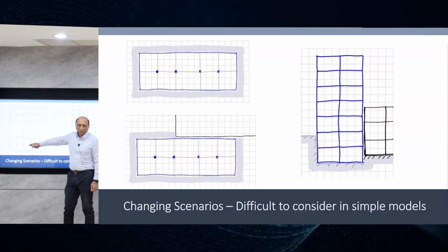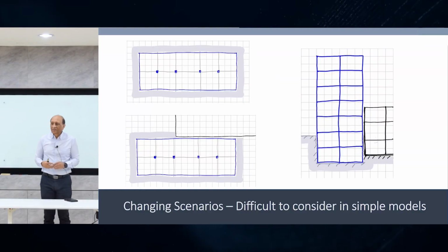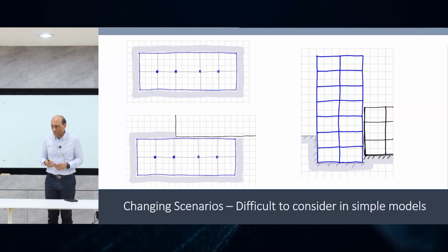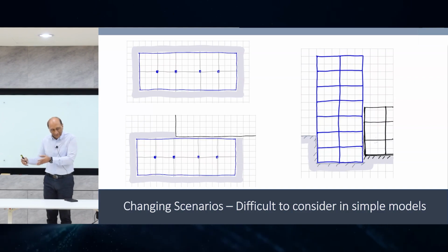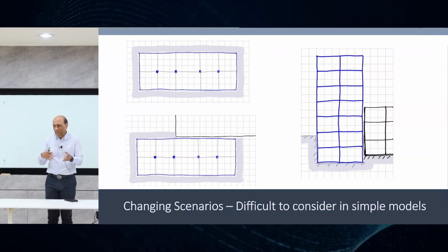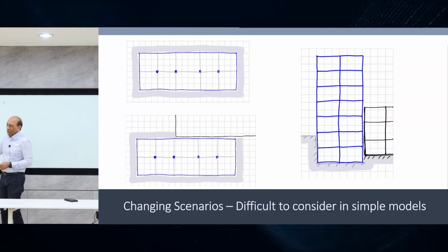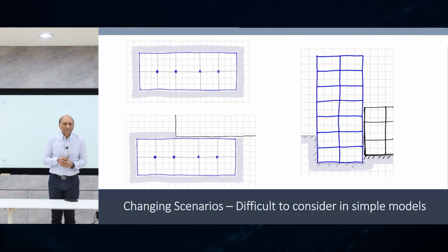Anything can happen. So you cannot make any reasonable assumption about the foundation, because today it will be like that. Tomorrow somebody will come, buy that land and start constructing, and it will change your assumptions of your basement design altogether. So engineers are at a loss what to do. If you include the soil because it is there, and in the future it isn't there, or if you don't include it and the soil is there, either way you are in trouble, because there is no simple answer for how to handle a situation like this until you do a few scenario-based designs.